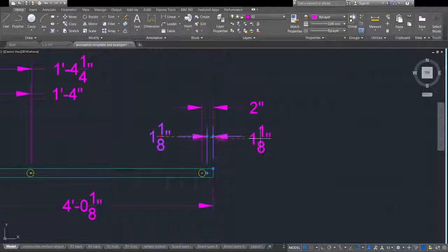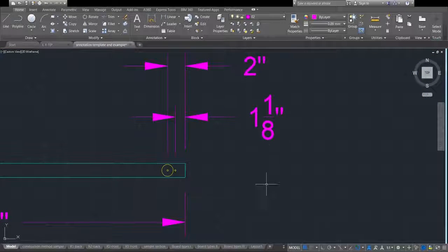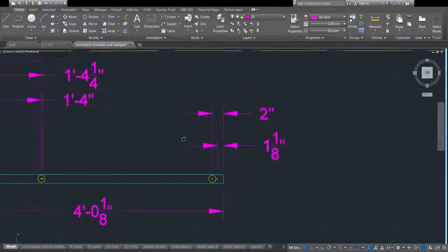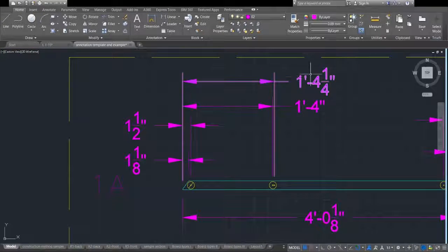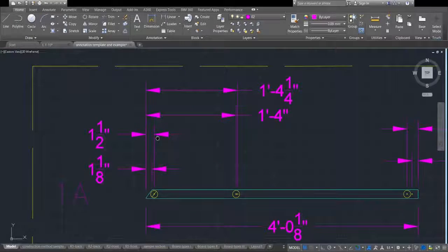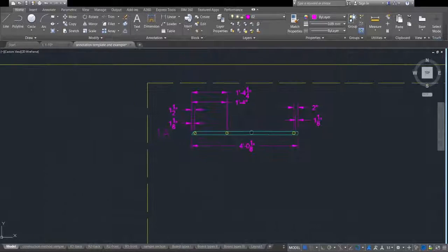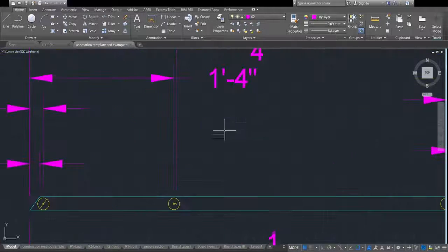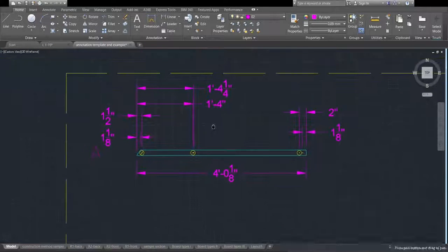Also, if there are multiple dimensions that share a line, then generally you want to make them on that side of it. So these two share this middle line here. So I'm putting them both on the right side of that, because the lines that are different are going to go on the opposite side. I didn't actually do this over here, because if I put all four of these dimensions on this side, then I would have to take this entire block and move it down. So I'm putting these over on the right, both to show that they deal with the stuff that's over here on the right, but also to help save space.